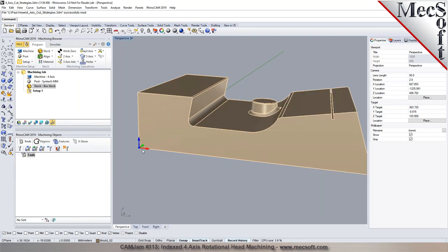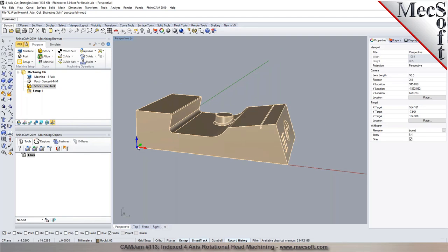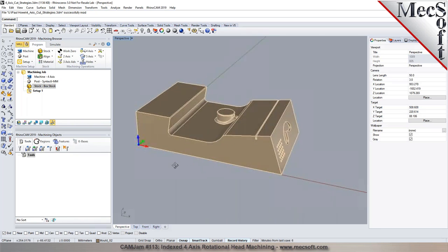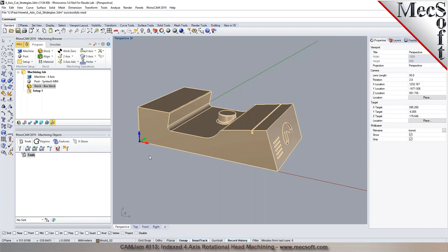So before we do that, we want to make sure that the origin, so we don't want to keep changing the origin. So once you establish the origin, it'll be the same for all your toolpaths, whether you rotate the head or you change the setups. So is this a good place to leave the origin, the southwest corner and the bottom? For clocking purposes, yeah, that'll be fine. Okay, all right, perfect.